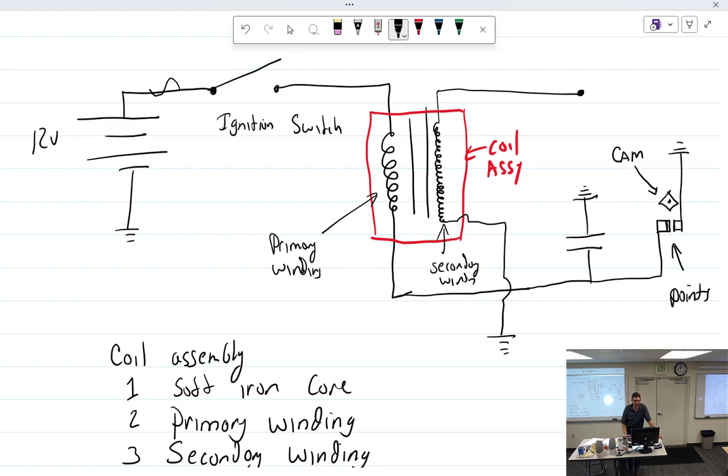All right. So we got to get that up to 12,000. That's how we do it. So 12 goes through here. Got 12 volts running to the primary. That creates a magnetic field that comes across, goes across the secondary. So when it builds up, we could get 20,000 volts, or when it collapses. The transformer works, but watch what this does.